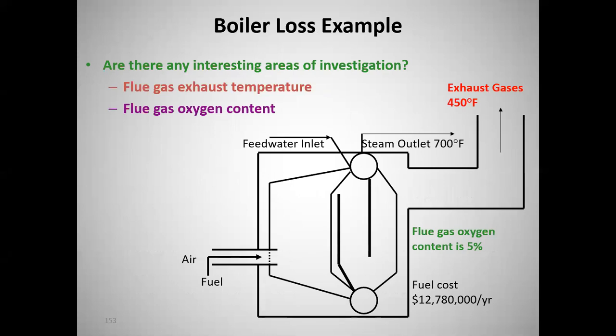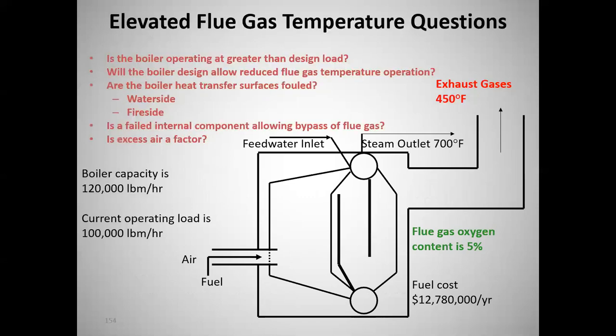Well, okay. So we've gone through the O2. What else do we see? I haven't adjusted my temperatures. I'm still putting up 450, and that's a high stack temperature. If that's the temperature I'm actually throwing away, coming out of the last heat exchange surface, that's pretty high.